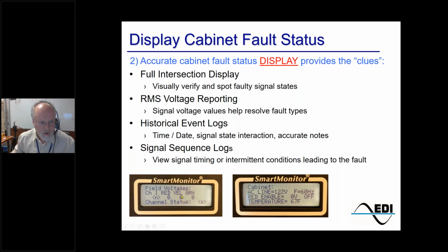Over time, it will get to the point where the monitor will start thinking that the light bulb is on, but it really isn't, because the monitor sees voltages like 25, 30 volts. So it's a nice way of going through and checking the status of your load switch. The other reason I bring this up is I've seen someone get a 13 or 14 here, and they say, well, I'm going to replace the load switch. They pull the load switch, plug it back in, and they're still getting the 13 volts.